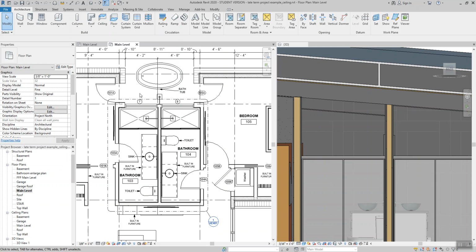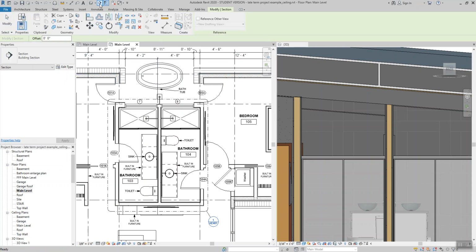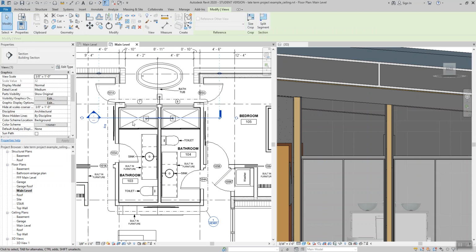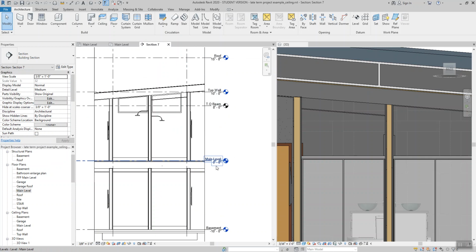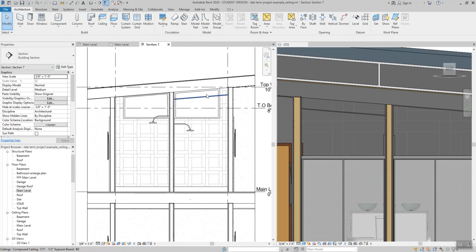And this is something that will be very helpful for you in Revit, to know that you could come up here to this little quick access section tool, click, and I can click, click, run a section through those bathroom walls, right? Click, click. I can create a section of that area, and I can view what I need to view, and when I'm finished I can delete it, right? How great is that? I can create a view, look at something, and then delete it. Okay, if I create a section, I don't have to keep it.